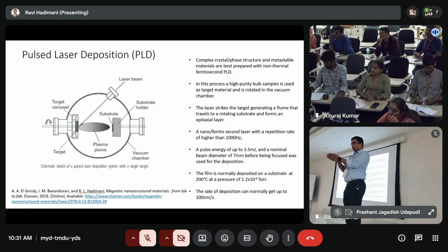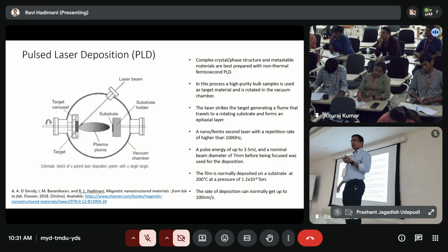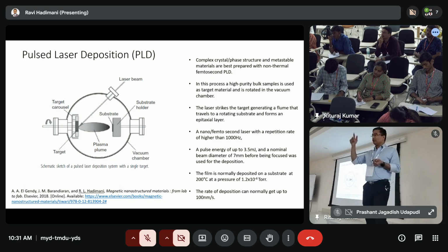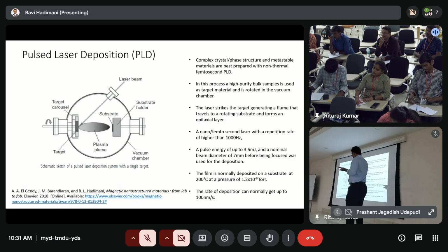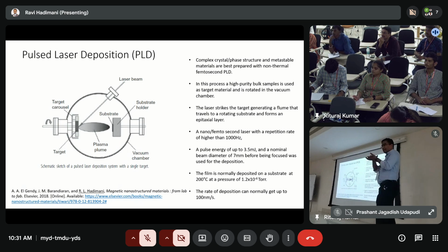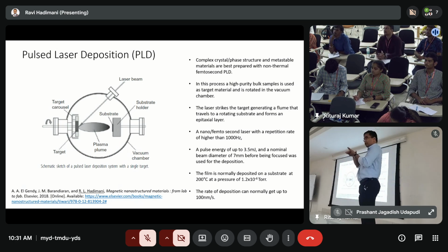It's not sustainable. So you get what is called Coulomb ablation. Because of the charge imbalance, you are knocking off, breaking the bonds. That is called Coulomb ablation. The previous one is purely thermal, where the phonon heats the material, whereas with the femtosecond laser, you are basically creating Coulomb ablation, or it's also called Coulomb avalanche, multi-photon interaction.